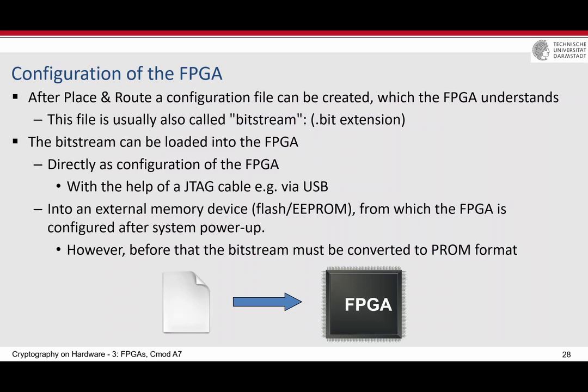There is a USB controller which also gives you the JTAG port. Then you can connect it directly with a USB cable, like this, to the PC. You are not only able to communicate with the FPGA that we will see today, for example, through UART communication, COM port, you are also able to configure the FPGA because it gives you the JTAG port and also the COM port. In some other devices, this is not possible.